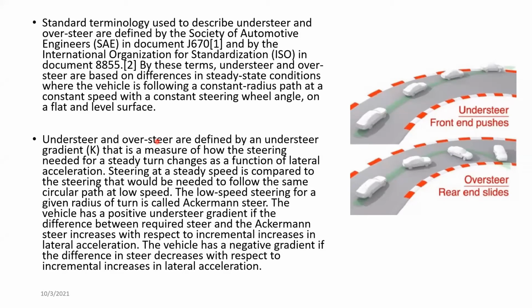But in normal day-to-day life, oversteering is a difficulty, because if we go too fast and the vehicle starts to lose grip, it's very difficult to bring it back. Understeer is known to be a bit safer. But this does not only happen because of the vehicle's steering; there are other instances where it could happen. One very good example is how the vehicle's power is delivered.